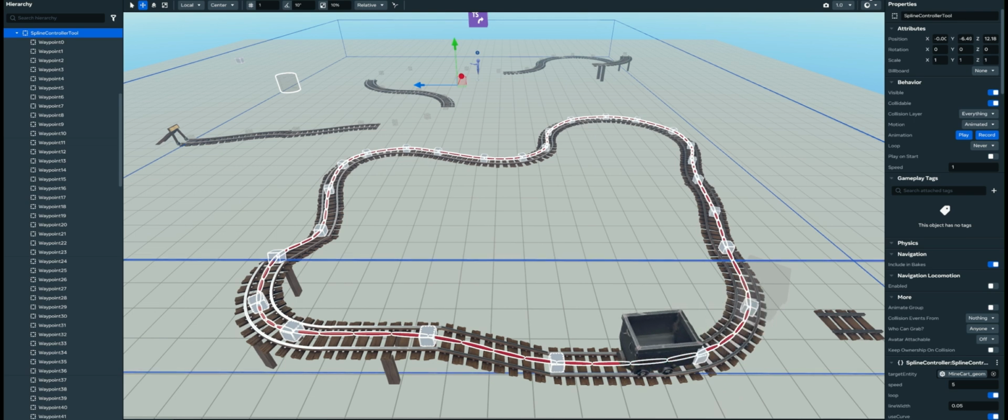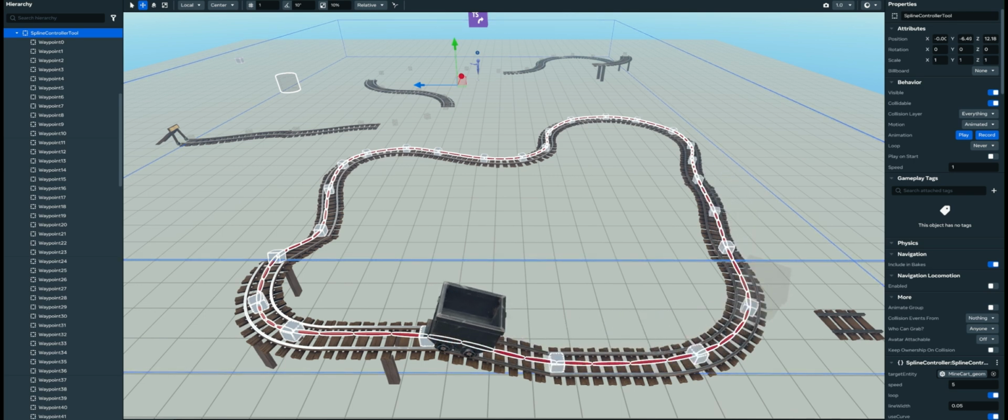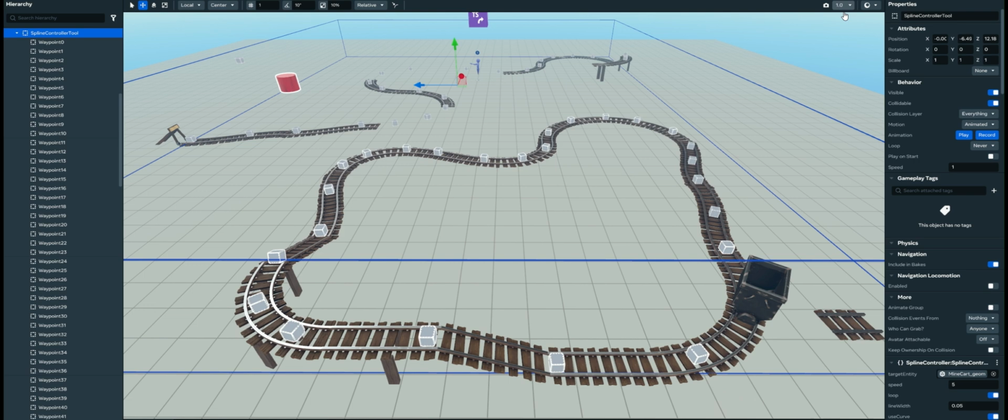Something to watch out for while using this tool is to make sure to use the first 4 waypoints. You might find if the limit is set to 3 that the lines will remain linear, although curved is selected in the properties. This will change into a curve once there are 4 or more. The formula uses 4 points to determine the curvature of a path. Keep this in mind.